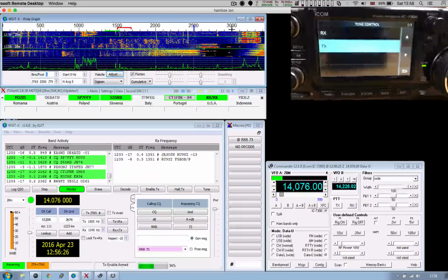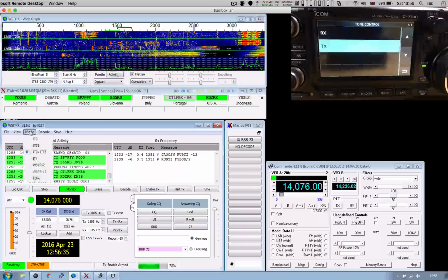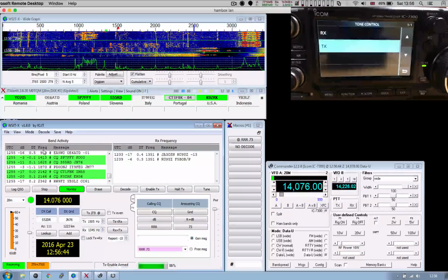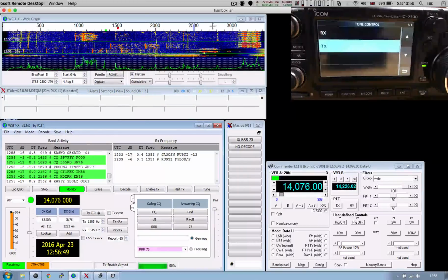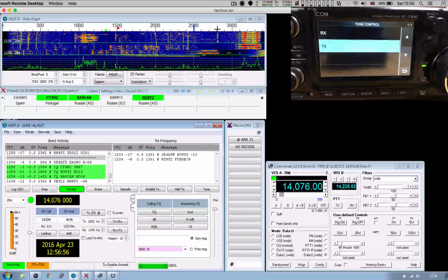Basically, if we want to transmit JT9, because we will see stations transmitting in this section, you have to either change the mode in here to JT9, which, if you look at the frequency readout below, just moves us a small QSY 2 kilohertz up, and that will fall within our filter. So roughly till 2700, 2800, you should be able to actually work those stations. 2900 is like the borderline. Anything here is actually a problem at this stage.